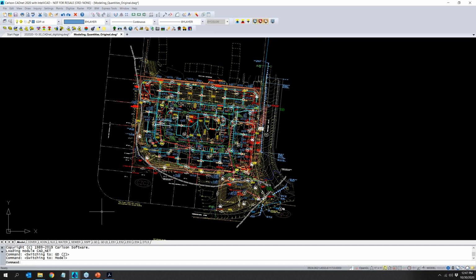When you're at the building stage where you've actually gotten the contract and you're ready to model it, most likely you're going to get a CAD file that you're still going to need a lot of work. The good thing is you should be able to find somewhere in here all your polylines and things. Are they going to be on good layers? Probably not. Are they going to be elevated? Maybe, maybe not. Is the geometry going to be good? Will endpoints connect? Will they be polylines? Probably not. So, you will have to do cleanup. You will have to do elevating 2D to 3D.